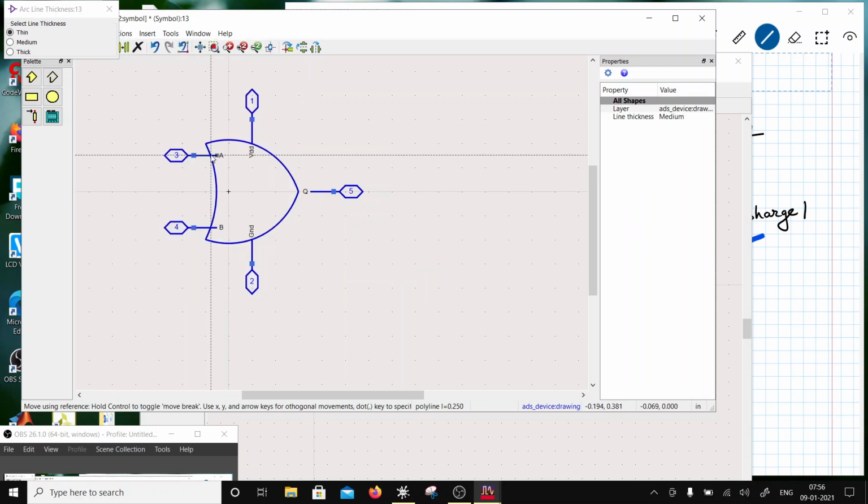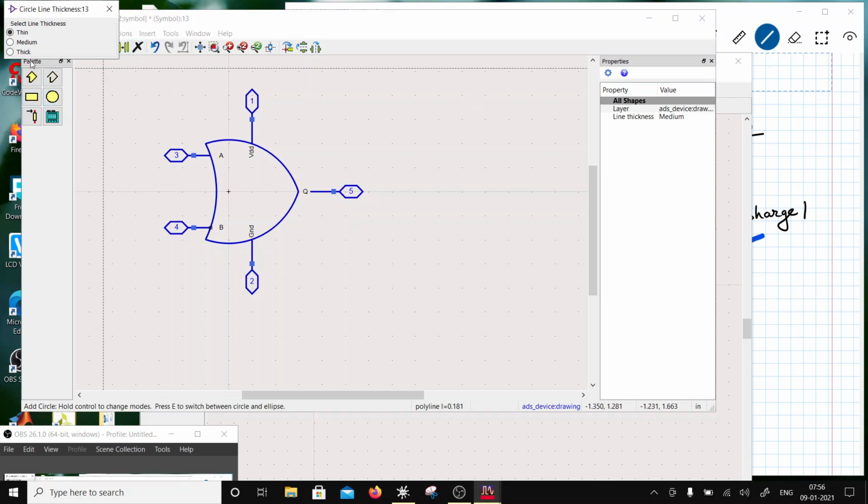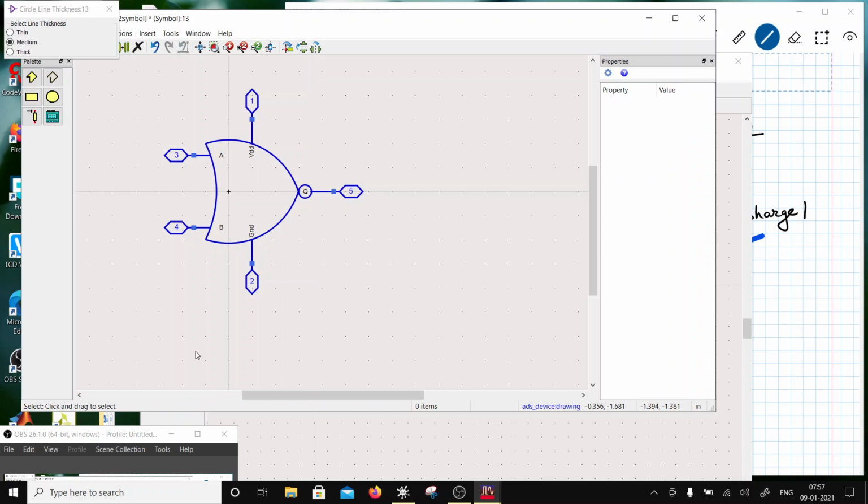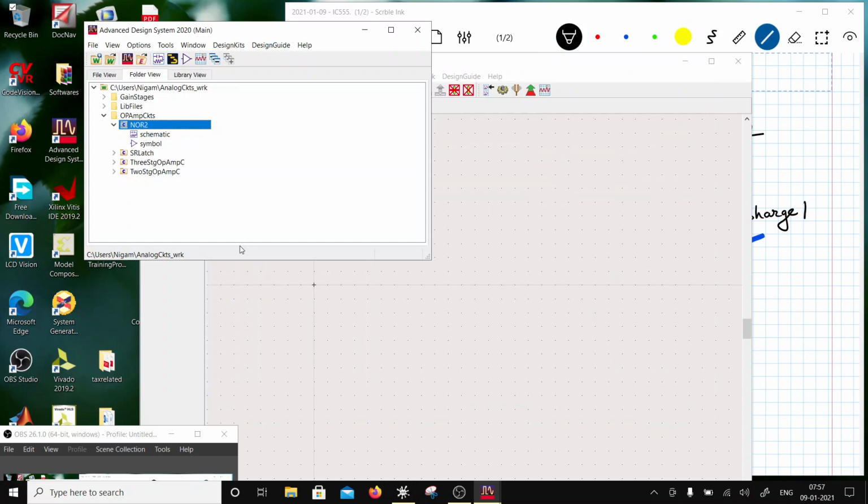and adjust this. So again, caution, don't move the pins with the grid off. Okay, so I'm also going to insert this guy, a small bubble over here. That's a small bubble here for the NAND gate, sorry, NOR gate, and I'm done. I'll turn back on the grid. So that's a NOR gate.